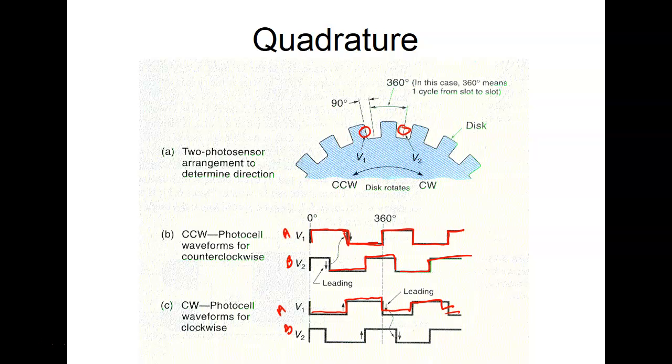If you leave power on, and usually we have no problem because they leave power on 24 hours a day, 7 days a week, as long as the robot's powered up, you're okay. It's just that something happens. So if they go over there to work on the thing and they kill the power on it, then they lose their count. You can recalibrate it, by the way, without the batteries in there, but next time you lose power, you're going to lose it again. So that would be a good thing they could do on preventive maintenance, just to go out and change them.